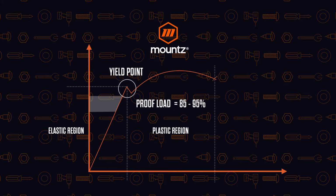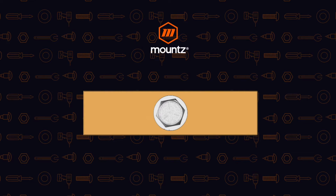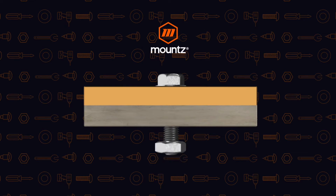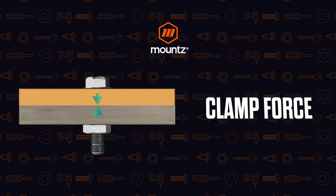And so when we say what is the clamp force, if we take a look at this animation, we've got a bolted joint with two pieces that we're trying to hold together, and as we tighten the nut, the fastener inside is stretching, creating the clamp force to keep the two parts together. So the fastener itself is acting much like a spring, but obviously the job of that fastener is to make sure that those parts don't move and they stay where they're supposed to.